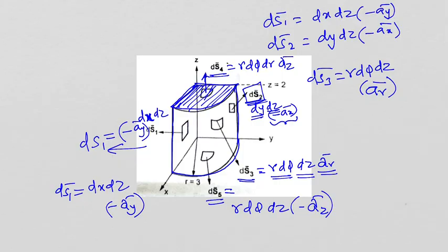In some of the computations, we could not keep Cartesian coordinate system components as Cartesian because some of them require cylindrical evaluation also. Over all the 5 surfaces, when we compute and accumulate the result, only the left hand side was obtained. As far as the divergence theorem is concerned, it includes the divergence of D over the volume, differential volume specified in the cylinder. So obviously del dot D needs to be computed, and then and there we need to change x, y components into phi and r components.